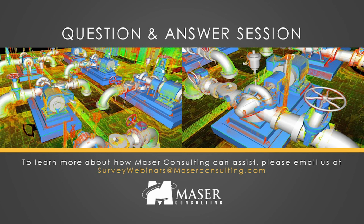And regarding verifying a conceptual design, yes, we can do that. If I understand your question correctly, if a concept has been built in Revit and they want to validate or prove that, provided we're in the same coordinate system, big word there, we can take the scanned information, the point cloud that CJ talked about early on, and drop it into the conceptual model and just visually look at it and see if there's conflicts or issues.